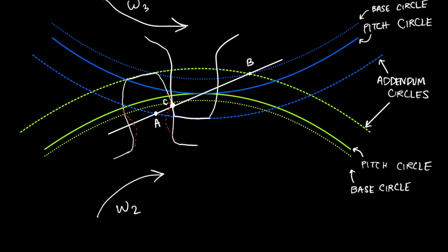So think about all this stress that's being built up in the tooth from this contact. We're kind of bending the tooth back this way with the normal contact force that's being experienced by this tooth. And when we do that and we eliminate some of this cross-sectional area that was carrying that weight, what we're doing effectively is making the stress go up considerably.